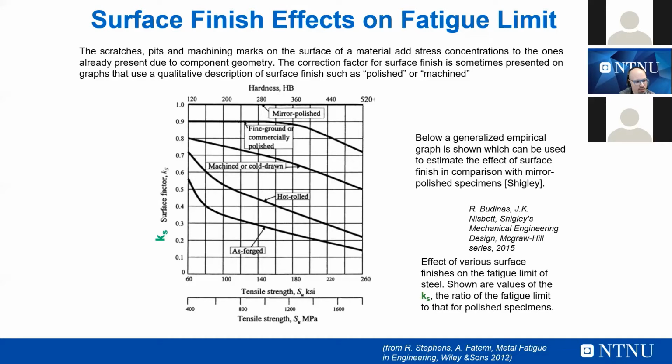This means that if you have a noble, a very respectful material in some way, you have to treat it very well. So the surface finish has to be improved. If you have common steel that is used for common construction, it is not so sensitive to the surface finishing.